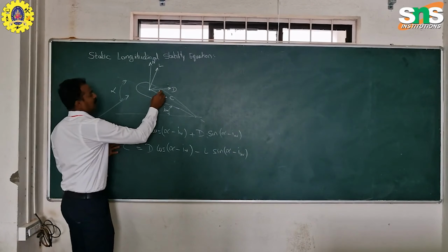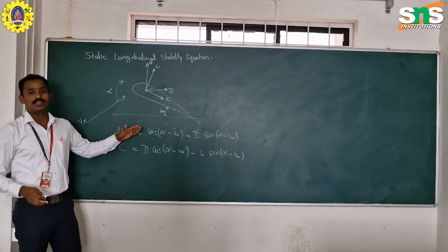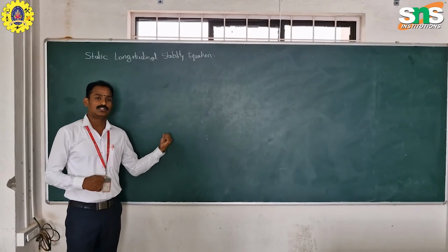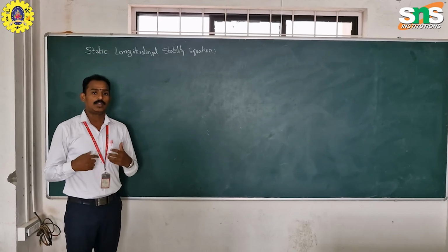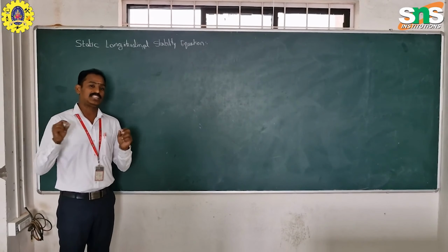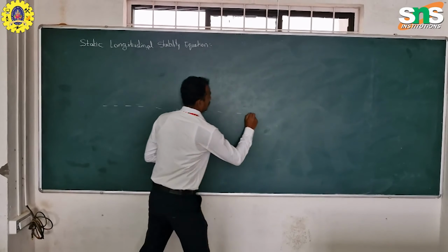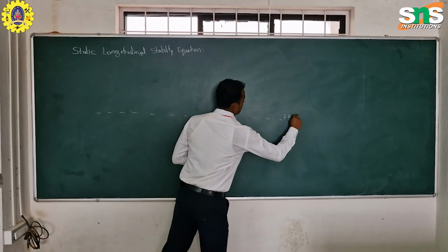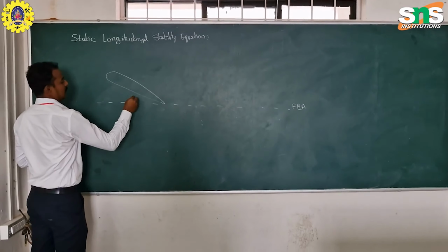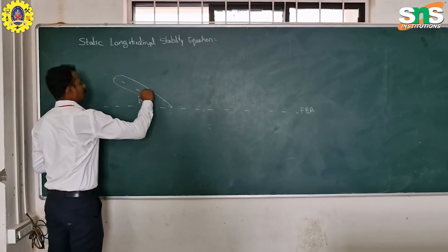So these equations come from the resultant of drag and lift in terms of alpha and i_w. We have derived the normal force and chordwise force on the airfoil. Now we are going to design an airplane, deriving the placement of the main wing and the tail wing with respect to the CG. Let us take a reference plane, the fuselage reference axis, and place the main wing at its incident angle i_w.